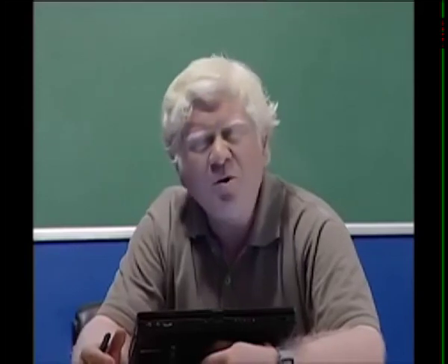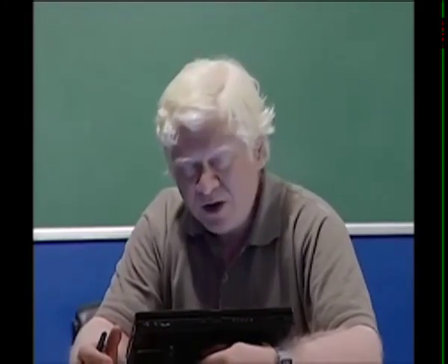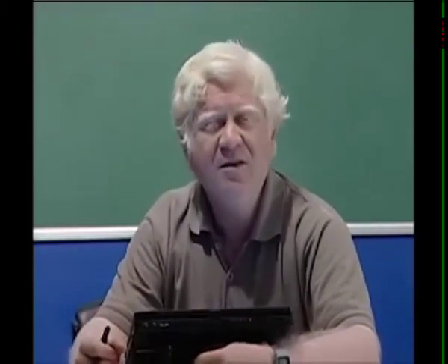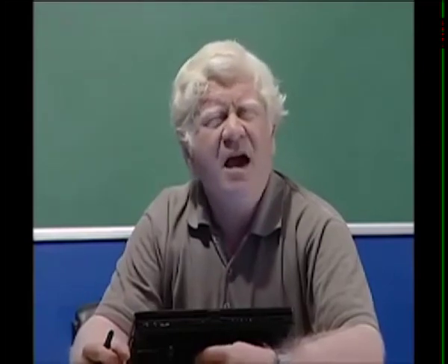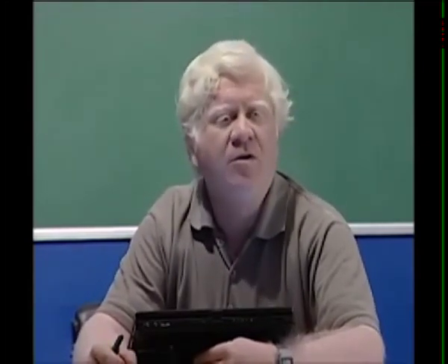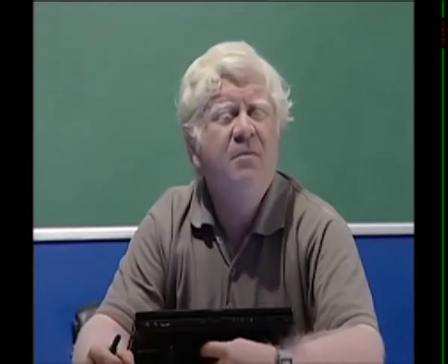From now on, we will not plot Fourier spectra for Fourier series using k as the index, but using k omega naught as the index, because the moment we do this, we have a handle on the actual physical frequencies that are involved. We would not have that if we just dealt with k and suppressed omega naught.